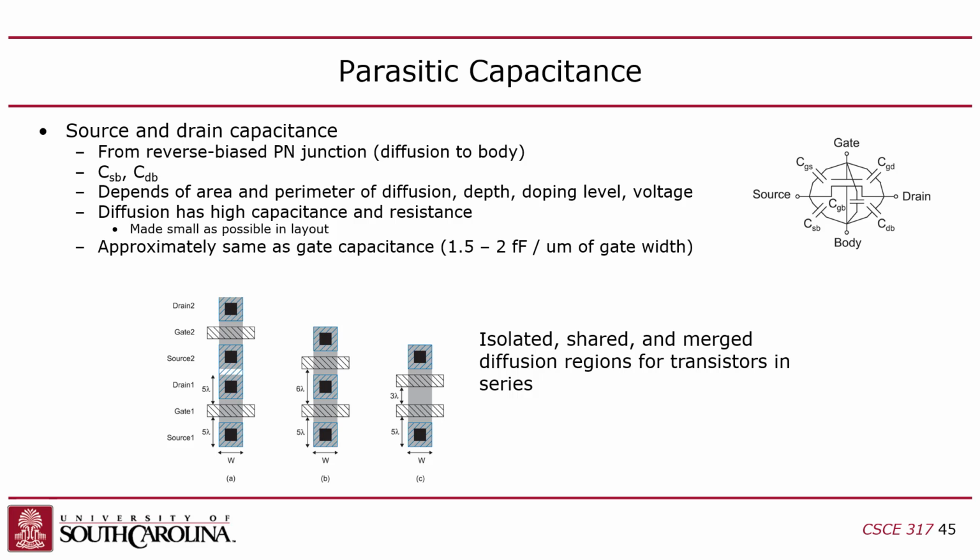Okay, so I can put two transistors in parallel here, right? You might say, how are those in parallel? Because the idea is that this gate would be connected. This would be one net. I would short these two gates, and so this side would go to VDD, this side would go to VDD, and the middle would go out. And so this would be essentially two gates in parallel. That's one thing you can do.